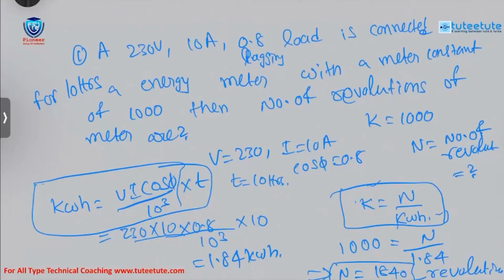Leading and lagging means: the main thing is just remember, wherever magnetic energy conversion is involved, there the power factor will be lagging. Just remember this simple concept. Wherever the magnetic energy concept is involved in any electrical apparatus or appliance, there the power factor will be lagging only. To overcome that, we connect capacitors.